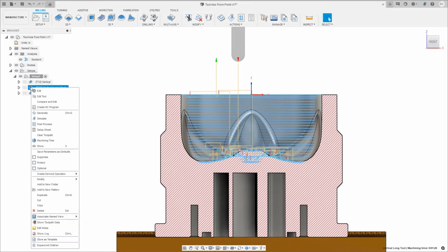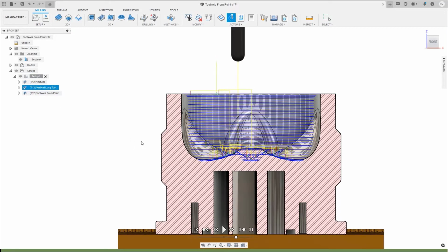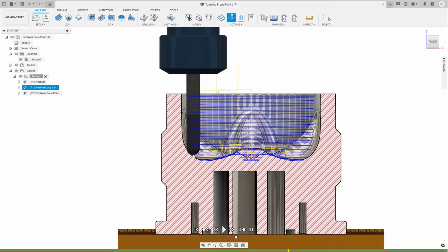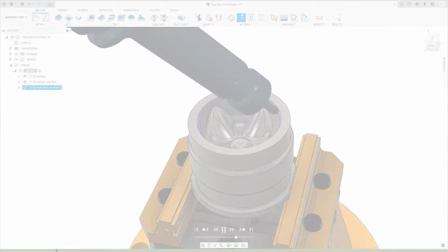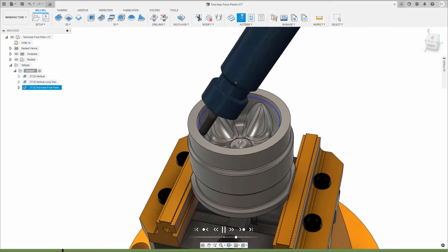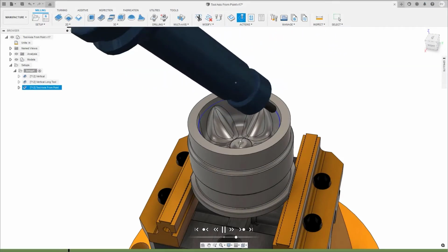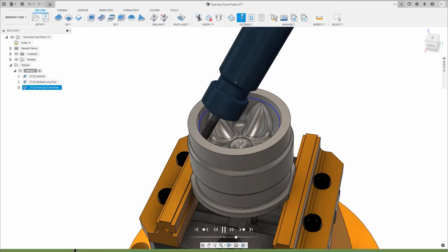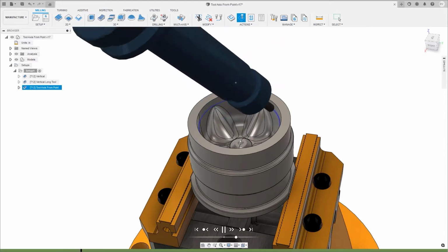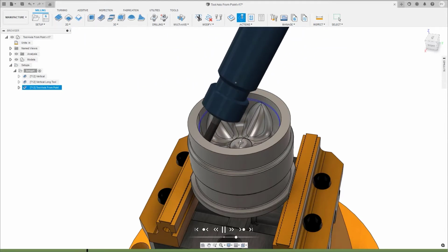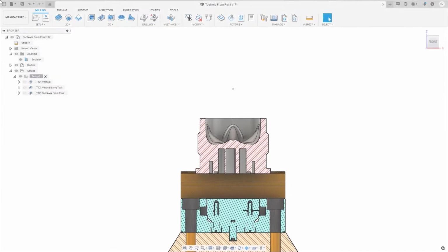While we could choose to extend the length of the tool for clearance, this may affect the surface finish and tool wear in an undesirable way due to the cutting conditions being less than optimum and tool vibration being introduced. By defining a different tool axis, we resolve issues like this, as well as create better cutting conditions, allowing clearance for the tool holder in addition to keeping the shorter and more rigid tool length during the machining process.